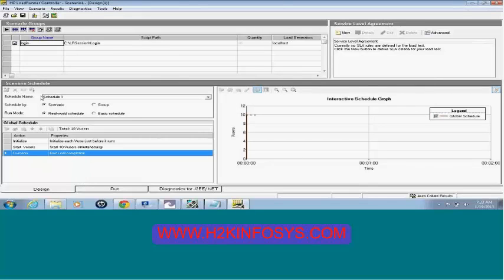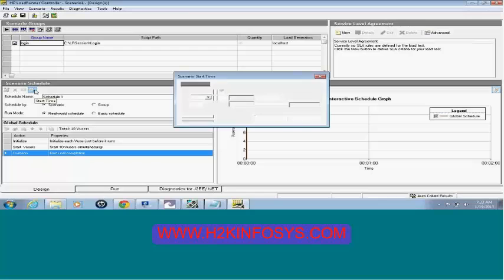Now go to the scenario schedule, and here you see there is a clock. Click on this button. This is the scenario start time, and there are 3 different options: without delay, with a delay of, and at a specific time.